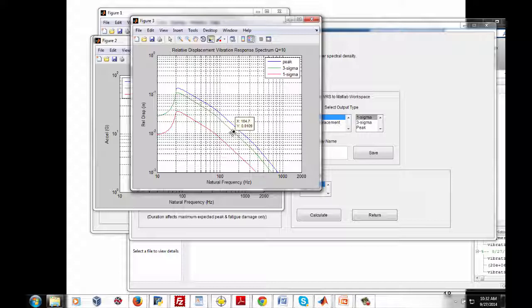But then if we take our natural frequency even lower, you can see that we're just in worse shape yet, and failure occurs before 20 million stress reversal cycles. So if our sole concern is relative displacement, we want that circuit board natural frequency to be as high as possible, given Q is equal to 10 and given the NavMat base input.